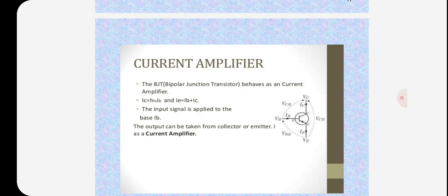The low resistance in the input circuit lets any small change in input signal result in an appreciable change in the output. The emitter current caused by the input signal contributes to the collector current, which when flowing through the load resistor RL results in a large voltage drop across it.